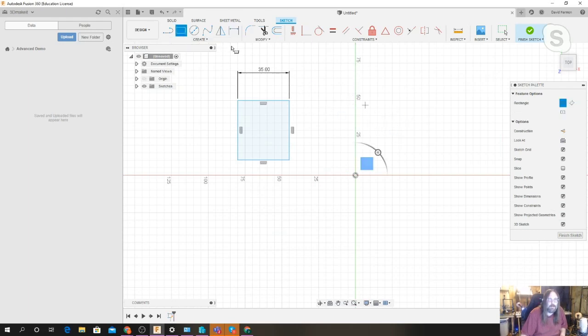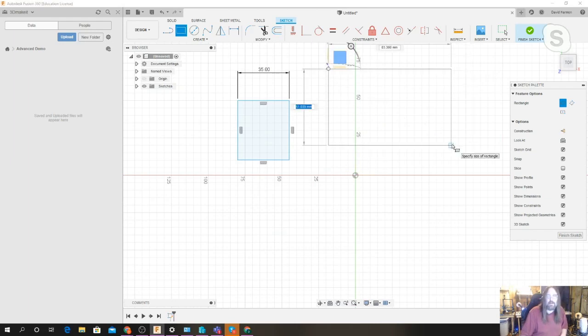So I'm just going to plop another 2-point rectangle. Oh, the shortcut to bring up that option is called dimensions, and it's D. It's just the D key. Very easy. You just push D. While you're making your 2-point rectangle, you can see on the sides, I can't move my mouse cursor because it'll move with me, but you can see on the top, in the middle, and on the left side in the middle, there's some number entries. They're highlighted in blue there.